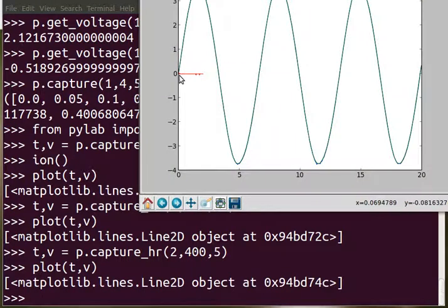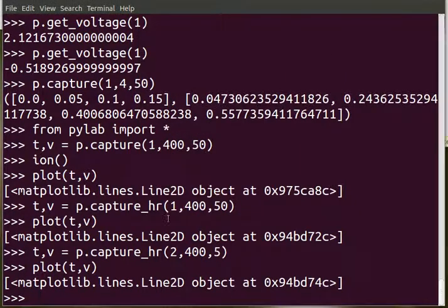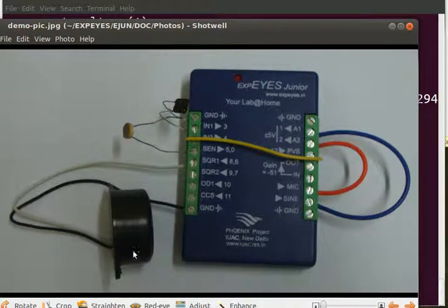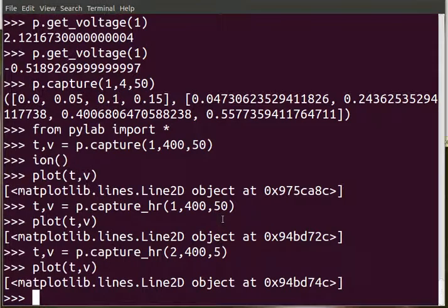You can see there is only a small line here and there is no signal there, so we will close this. And how to get some signal there, that is the issue. For that we need to send something to this, like we have to energize this square one and generate a square wave here. That can be easily done here. P dot set square one, say let us put it as 3800 hertz.